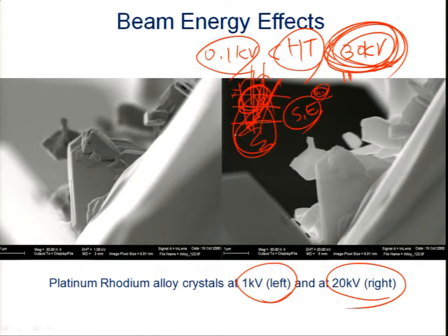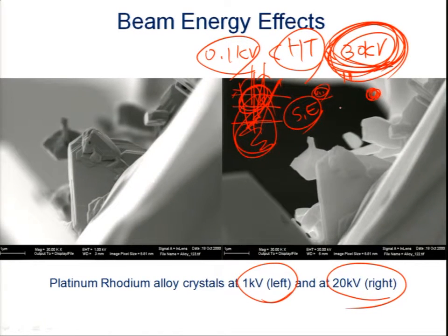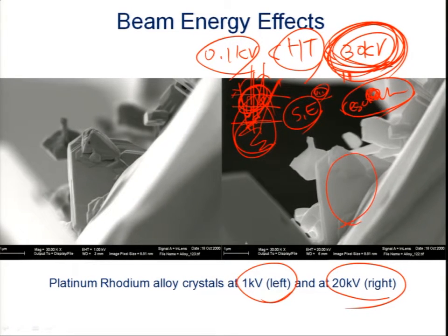So when you need to observe very small structures, the high electric field of the electron beam provides much better resolution. But in this case, the secondary electrons also come from a little bit deeper in the surface, so you start to lose some of the details from the surface.